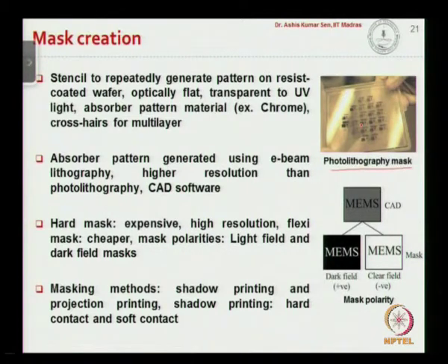A mask is nothing but a stencil to repeatedly create a pattern on resist-coated wafers, and these masks are optically flat because they have to be put together with the surface of the substrate, which is flat. The material that we use to generate this mask is typically optically transparent.